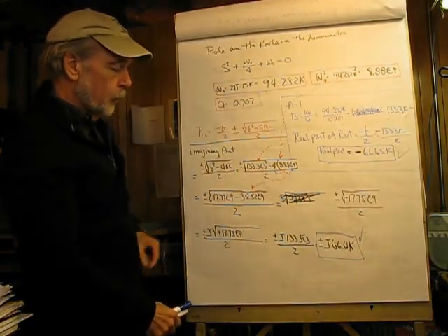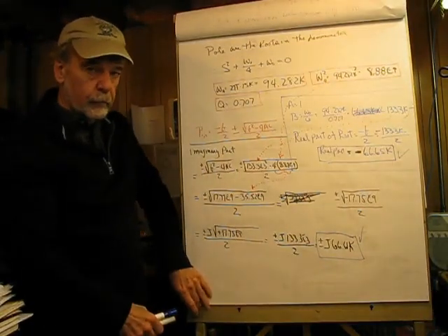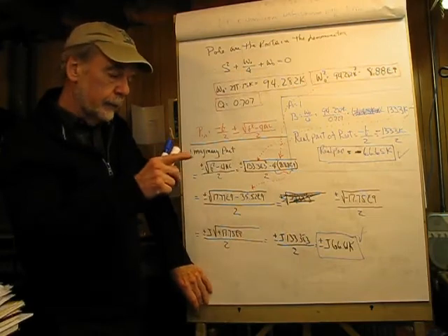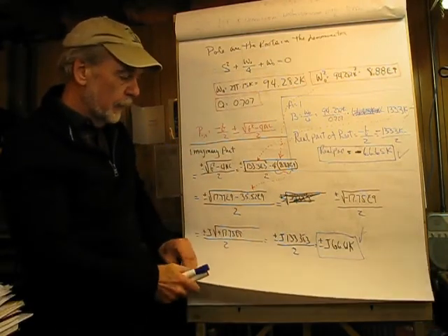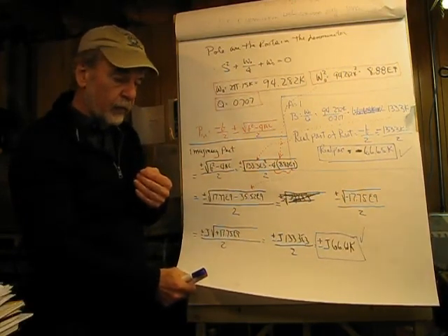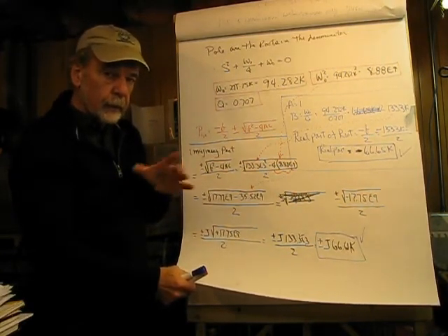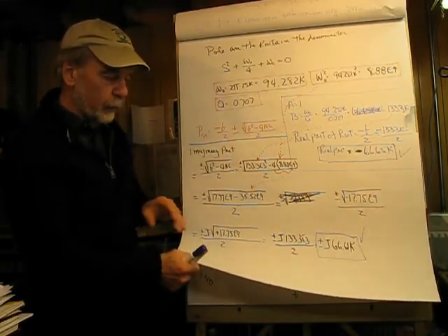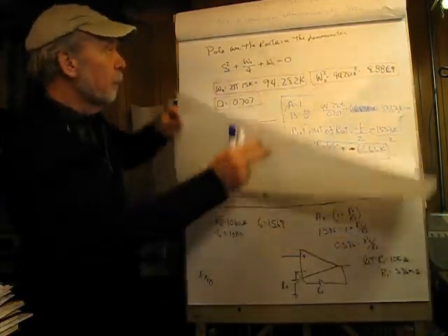Now if you draw this in Multisim, it'll give you the poles also. You go to Analysis and then down to the pole-zero plot, but it's restricted in range from the critical frequency 0.5 up to about Q equals 2. It won't give you answers outside of that range, which is kind of unfortunate.